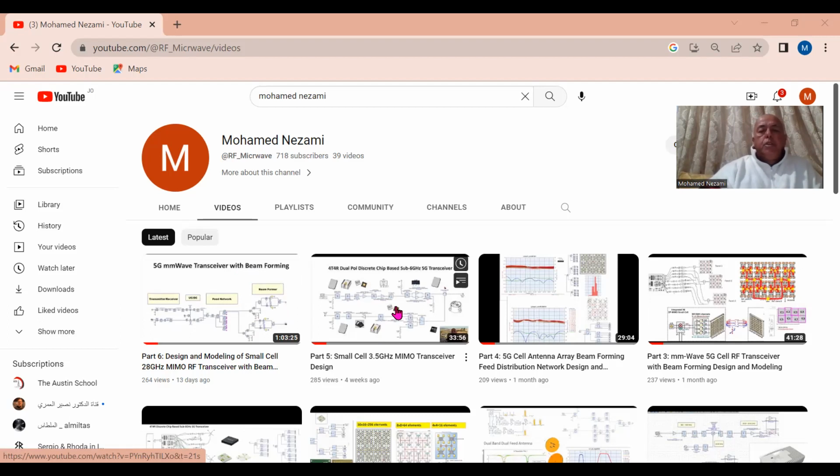And as a first step in designing a circuit board for this small cell RF transceiver system, we would use PathWave to do a system analysis. Based on that, we have chosen off-the-shelf parts that you can purchase from distributors on Alibaba, or Mouser and DigiKey.